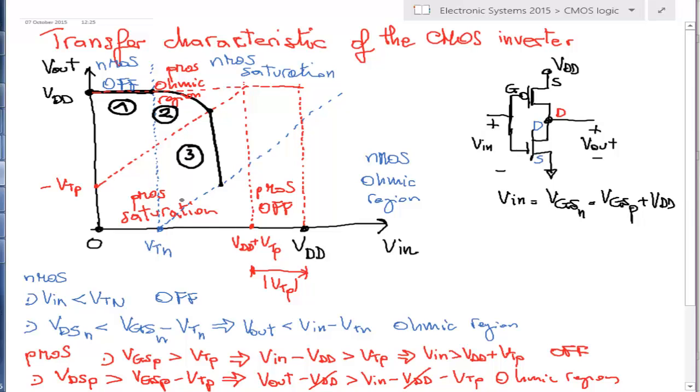You know that when a transistor is in the saturation region, you can use the small signal models. The small signal models that you have used during your course in electronics are only valid in saturation. Now we are exactly in that situation because both transistors are in saturation. Let's try to use the small signal models here.